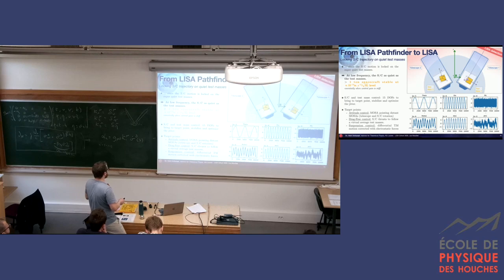So you have four control systems. One is called the attitude control. You need to make sure that the spacecraft is well oriented, so that it points towards the distant spacecraft. So you have control of the overall orientation of the satellite, and control as well of the opening angle of your MOSA. Typically, when you see both MOSA deviate at the same time, it means you need to actuate the satellite itself to correct it back. But if one is well aligned compared to the incoming beam and one is deviating, it means the two MOSA need to rotate. So you always have a differential mode and a common mode. Common mode, you act on the spacecraft. Differential mode, you act on the telescopes independently.